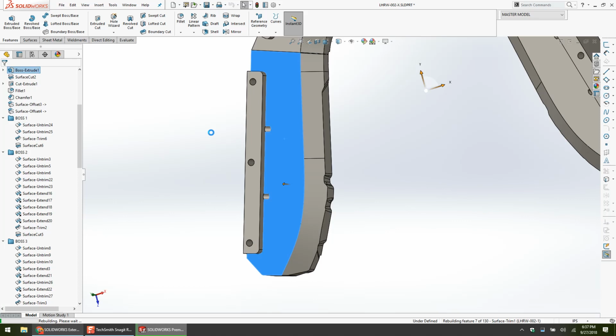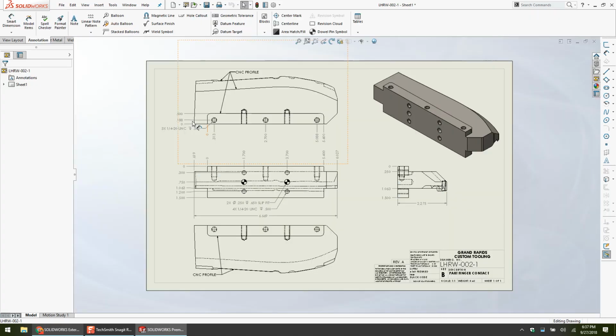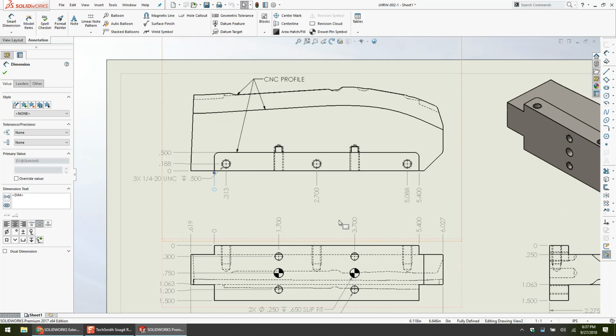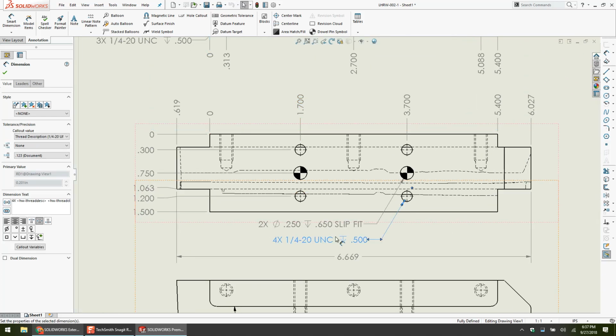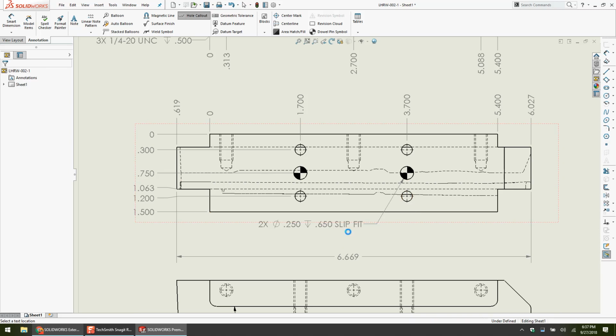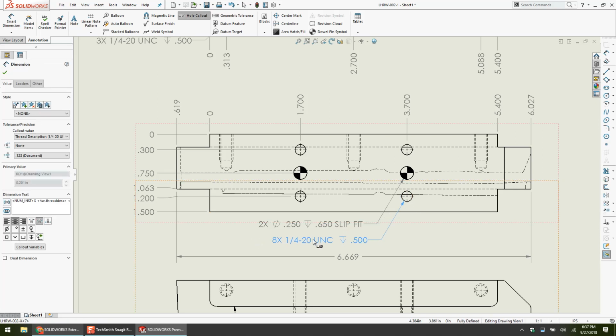So you can't just right click and say open drawing. No, because it's a configuration, and because SOLIDWORKS is looking for a drawing of the same name, it can't find 002-X. So my drawing is 002-1, 002-3, so on and so forth. So you are correct. That's not the one we're looking at, this one. So I don't know. If we delete that and re-add it, yep, there's 8. So I overwrote it to 4.